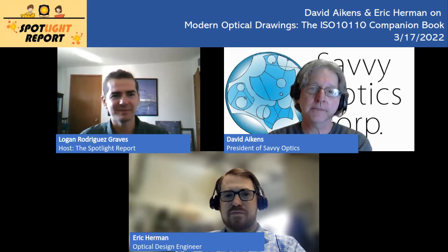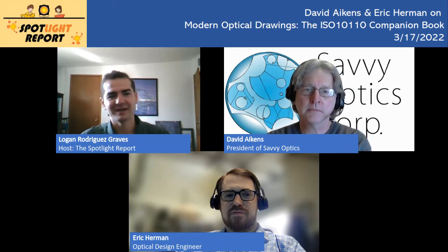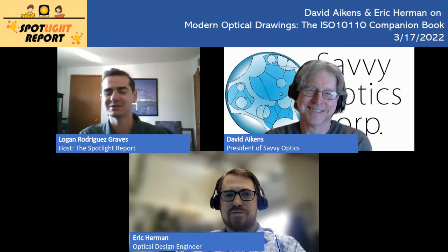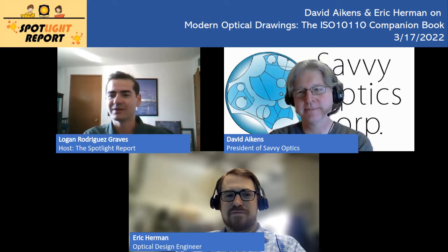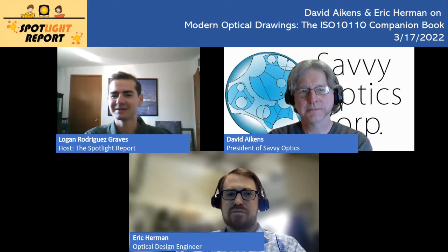Yeah, and as you said, there are a lot of tolerances. Even just going into chapter 2, optical materials, it's material properties or refractive index, stress birefringence, bubbles and occlusions, homogeneity, striae, and that's just 2.3, right? So there's several sections in chapter 2. And I think that's a great point, that if you miss something, there is still a backstop. It's not just up in the air of, however I make it, I make it.